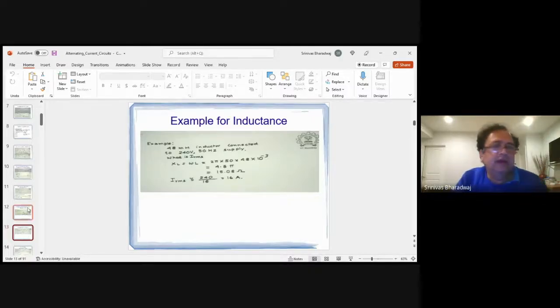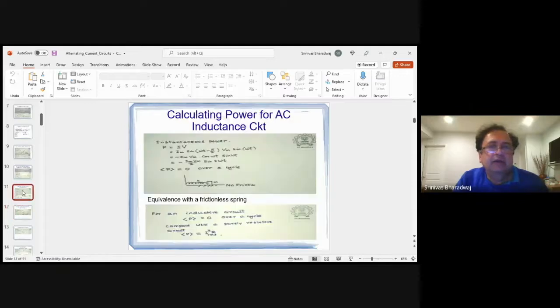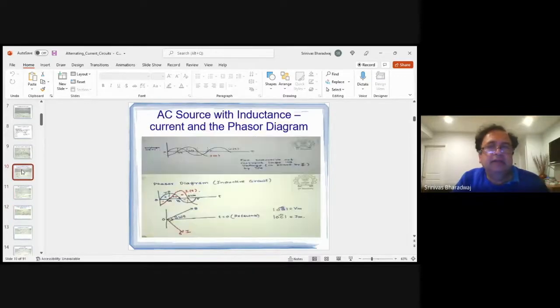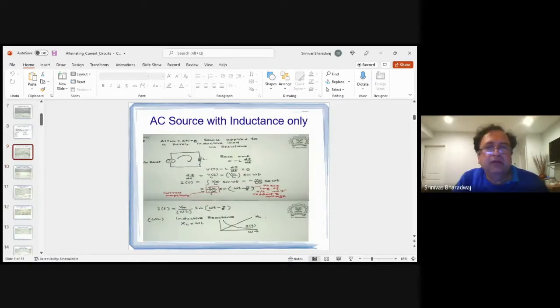Like, so you can look at this value, right? L, like you can think of this as a resistor, right? If you leave out the phase lag, if you did an RMS of this, the corresponding value there can be thought of as a resistance. Vm by R sine omega t, right? Here it is Vm by L omega.